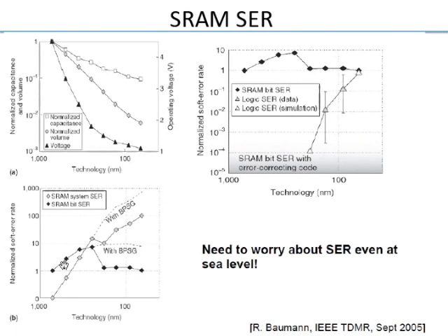even though for a single SRAM bit, the soft error rate they have managed to maintain somehow by various tricks, overall, for the system with all the SRAM bits, the number of bits in the SRAM is also going up. So for the overall system, the soft error rate is going up. So because of this, when you